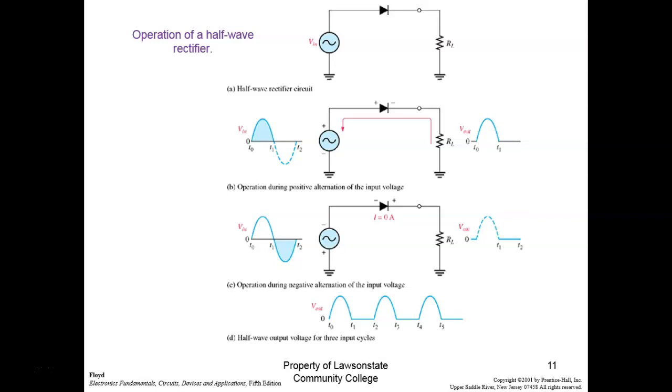The diode. So when my AC goes, when this goes negative, what would happen? This guy would be reverse biased, which would cause zero current to flow. The resistor would drop no voltage. I get no work. Then during the positive alternation, the diode is forward biased. Then it would let the positive alternation come through. So I get 1/2 of the work, right? You understand? So one time we're getting 0 volts, the other time we're getting 2 V peak over pi. So we end up with V peak over pi.